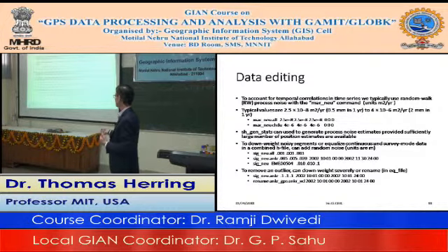So if you change the antenna, we'll often call that 2PS, 3PS. If there's an earthquake, the PS part gets changed to a 2-character code. And so we have a special code of XCL, which means exclude. And there's also an XPS, which also excludes it, but in a slightly different fashion. So this is a way to actually take the site completely out of the solution. You don't see it anymore. It's completely eliminated from the covariance matrices as we go across. So if it's really bad, this is what we recommend. If you still want to see the value somewhere in your time series with big error bars on it, then that's a technique that you can use.